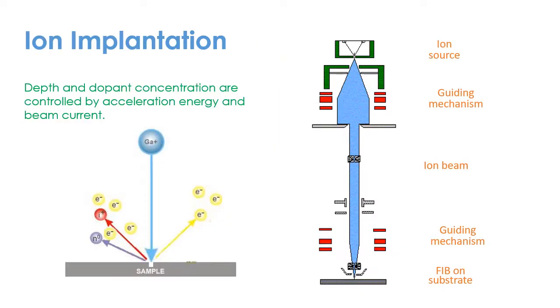Ion implantation is a much more extensive process and requires special equipment compared to diffusion. Implantation is accomplished by accelerating the ion through a high voltage field of as much as 1 million electron volts, and then choosing the desired dopant by means of a mass separator. In a manner similar to that of a cathode ray tube, the beam is swept across the wafer by a set of deflection plates, ensuring uniform coverage of the substrate.